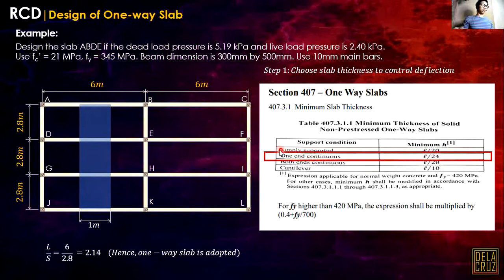Okay, so on the first section, simply supported. Now, as we can see, the slab is not simply supported. The slab is assumed to be fixed when it is attached to a beam. So in this case, our slab is fixed all around. That is the assumption of the code, unless the problem specifies that it is not fixed or is just resting on a wall. But in most common cases, it is fixed.